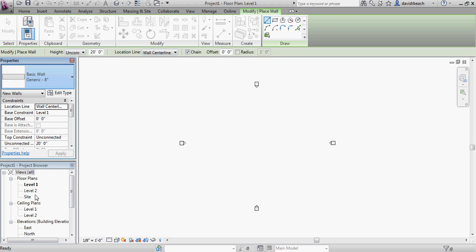Now there are two other default wall types, exterior glazing and storefront. In particular, storefront is going to make a lot of assumptions for you. It's going to pre-place mullions. Everything's going to be locked in place, or actually pinned in place is the technical term. And so typically, as a designer, we're going to stick with curtain wall 1 as our default wall to use.